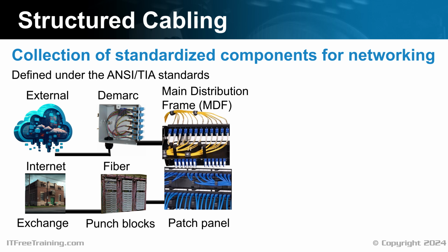Usually the first group of punch-down blocks will be the incoming lines. The upper block numbers are going to the cabling running to the customer's patch panels or their internal wiring. As businesses grow, there may not be enough punch blocks, and more are then added. As existing punch blocks become full, newer external lines may need to be installed at the end of the punch panel rather than at the start. Don't assume that external lines will always be the first punch blocks. Most MDFs will have documentation to explain what wires go where, but often this documentation is not kept up to date, so don't assume anything.